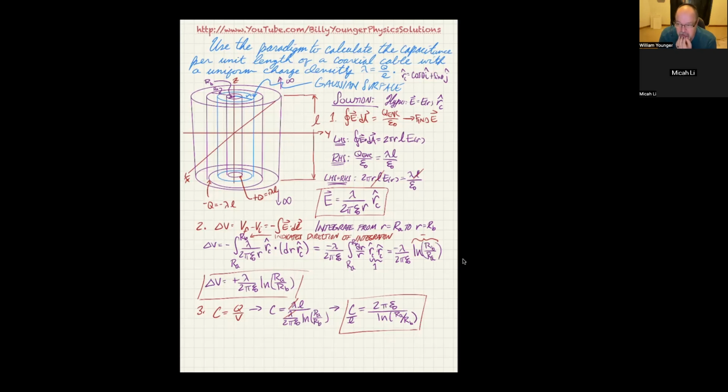There's some good stuff to learn in there. Simpson's a good book, and Abramowitz, or not Abramowitz, I'm trying to remember the name of it. There's two really good books on that. But one thing we did, for instance, with op amps that you might like is you can make an op amp circuit to match a differential equation. If you connect the op amps with a voltage source, the oscilloscope will show you the actual graphical solution of the differential equation. That's one of the cool things. You can do integrating circuits, differentiating circuits, adding, subtracting, multiplying, dividing, and from that you can make up a whole equation, put in the input, and out pops a solution to a differential equation.